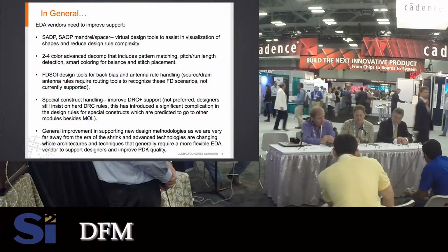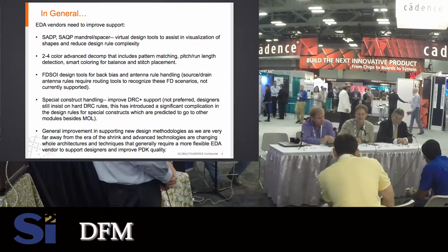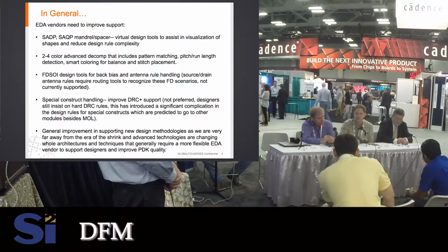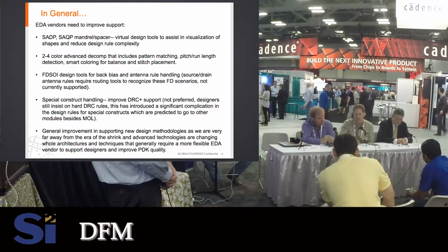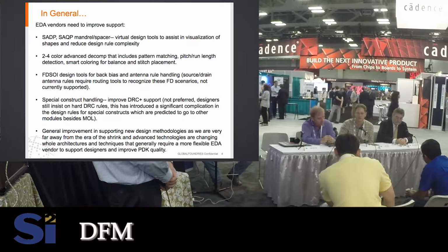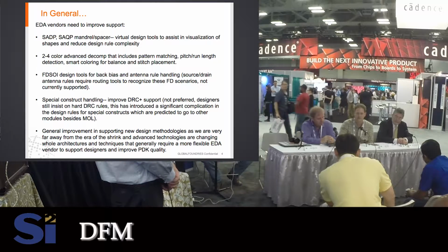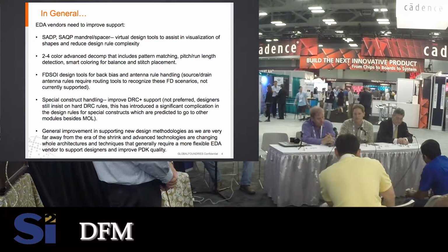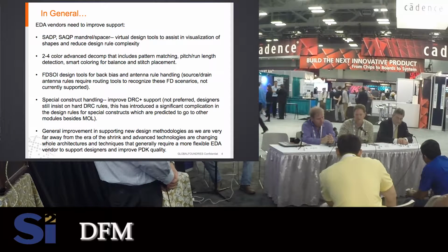But then that identification that you use on the schematic side has to be translated to the layout accurately every time. You cannot have any mistakes. So you often tie that in with the LVS flow to verify that you're placing the same voltage marker on those same circuit nodes in the layout as you are in the schematic. So all of it ties together. And when you get to the layout phase, you have design rules, just like any other metal layer or active or in-well spacings. You have to identify those circuit nodes that have that voltage designation, and then check the relationship of those layers to other layers that you care about.